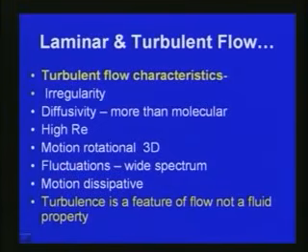So in most laminar flow the rotational effect will be very minimal, or it can even be irrotational in nature, but all turbulent flow is rotational in nature. Due to this, most of the time we have to consider the fluid flow in 3 dimensions, since in one or 2 dimensions it is very difficult to see what is realistically happening, how the disturbance takes place, and in which direction it takes place. So as far as turbulent flow is concerned, we have to do 3-dimensional analysis.